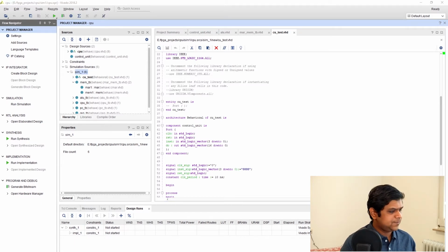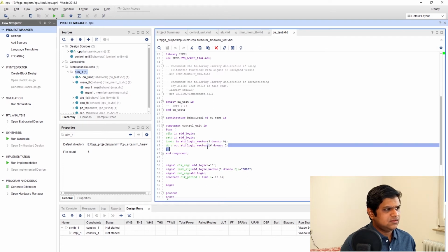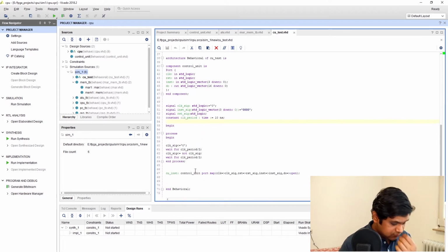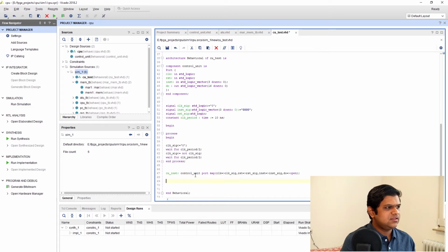Now we have these 17 control signals, 16 down to 0. We have to set these control signals depending on our input instruction and depending on what micro step we are in within that instruction. So I have taken this in this order. First is halt signal, then we have output in and output out. That is, we have an output register, so to load that we will enable output in, and to output that output register to our data bus,